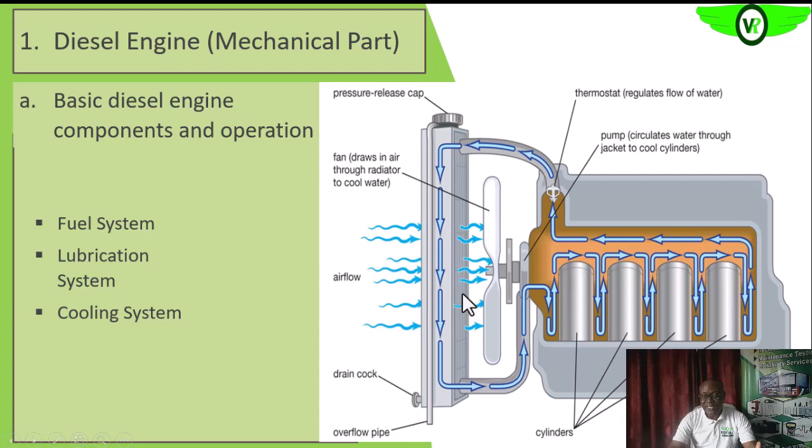But basically, that air that is forced through the fins comes into contact with the fin. So the heat that has been transferred by conduction onto those fins is extracted by that air, also through conduction, and taken off into the atmosphere or wherever you want to send the hot air to. Okay, so the radiator's function is to do the work of exchanging the heat to the atmosphere.